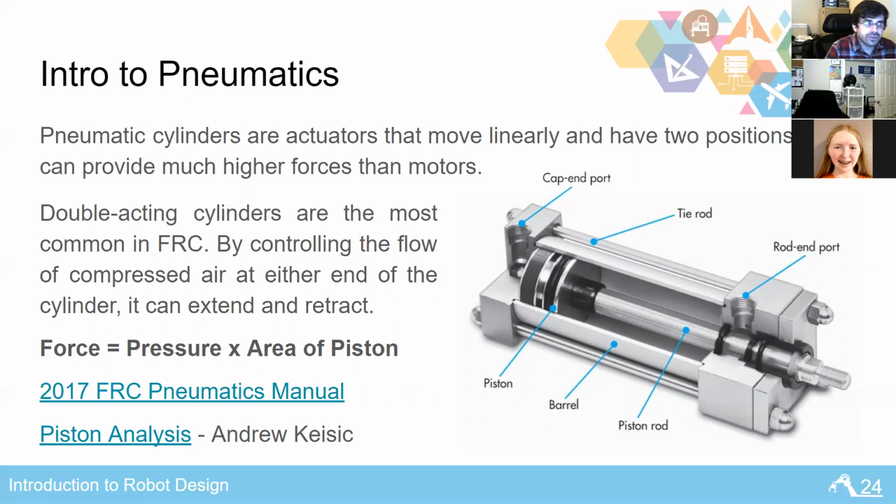So if we only need one cylinder on our robot, that usually isn't enough of a reason to add all that extra weight. We might say, well, how can we do that with a motor? Because there usually is a way, it's just a little bit inconvenient. But if we know that we're going to have 2, 3, 4, 6 cylinders on the robot, then it's definitely worthwhile.